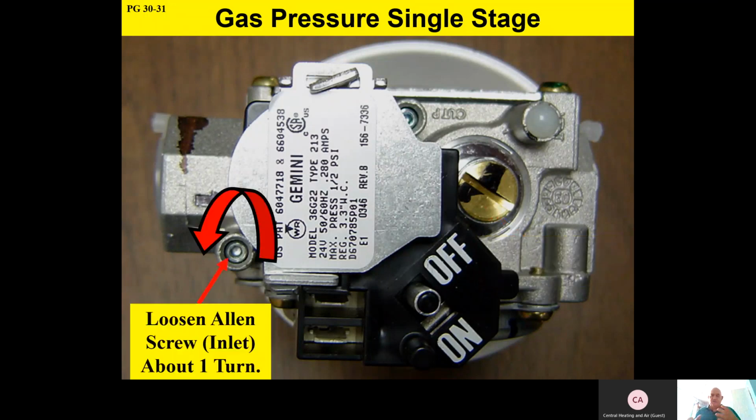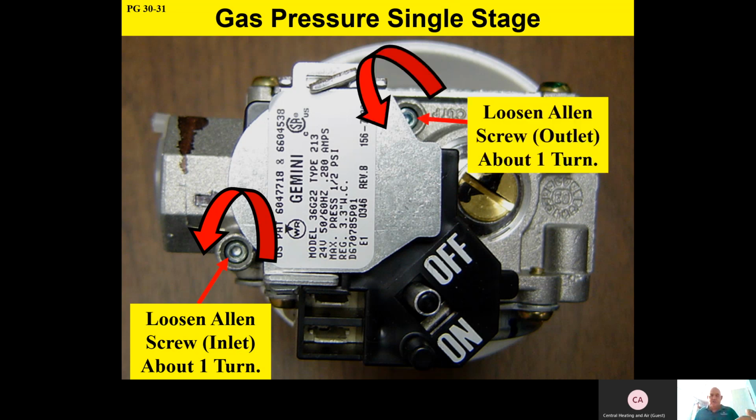You'll then loosen that little Allen screw about 1 turn, and then slide your hose over it, and then turn the gas back on to read your inlet pressure. And then there you'll find that there's the outlet pressure to your manifold. Again, you'll just loosen that little Allen screw about 1 turn, and then slide your hose over it, and then turn the gas back on. Then you'll be able to read those pressures on that single stage valve.